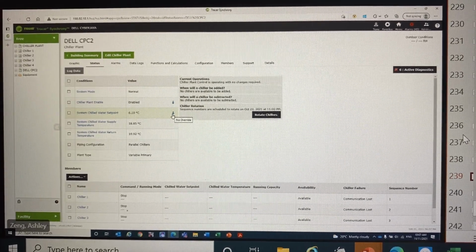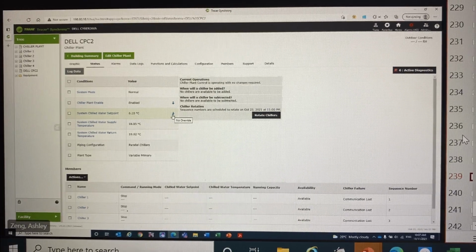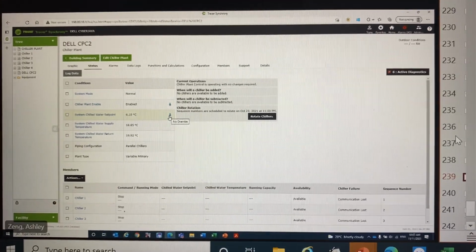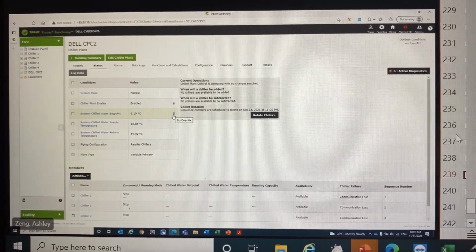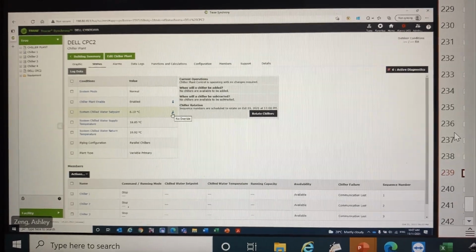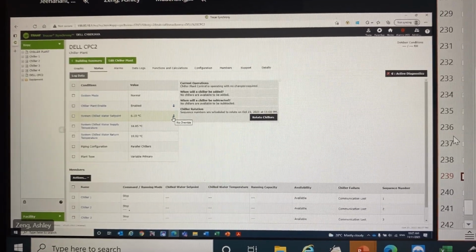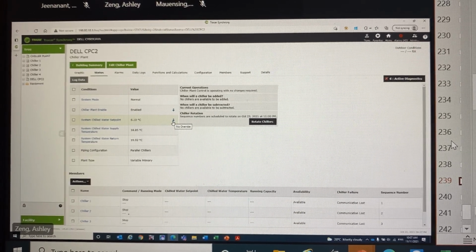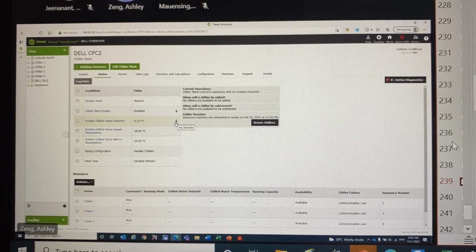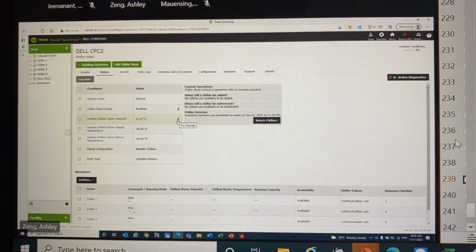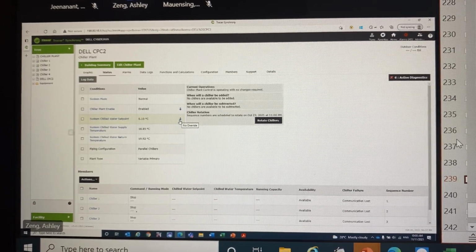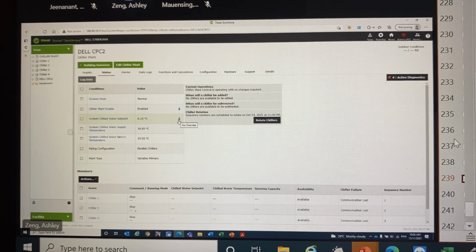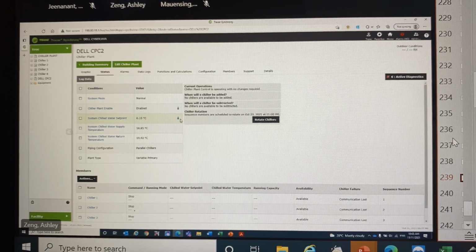So if, let's say, the user overrides this to 10, then yeah, this is going to call your chillers. If you tie this system chilled water set point to your chiller set point, it's going to call the chiller to run at 10 degrees. Then your air conditioning units will also change accordingly with reference to this system chilled water set point. So this is a very important parameter that we do not really want the users to override. When you hand over the system to your clients, you have to tell them to try not to make changes to these things.